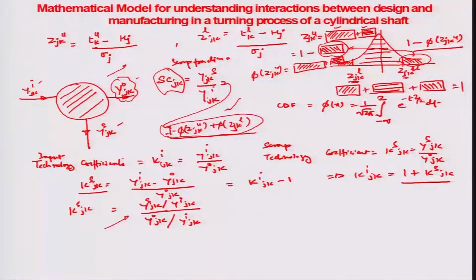So, without doing any real experiments again, if I knew the process mean, the standard deviation, and the tolerance, I should be able to glance at a normal table and look at this particular value, which is percentage reject.